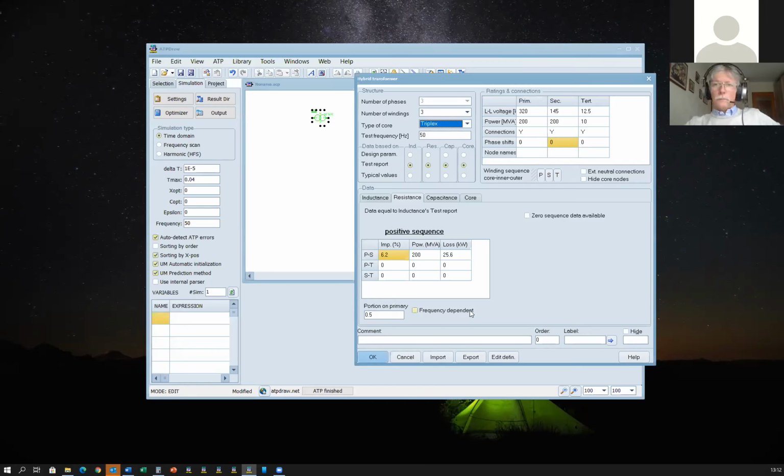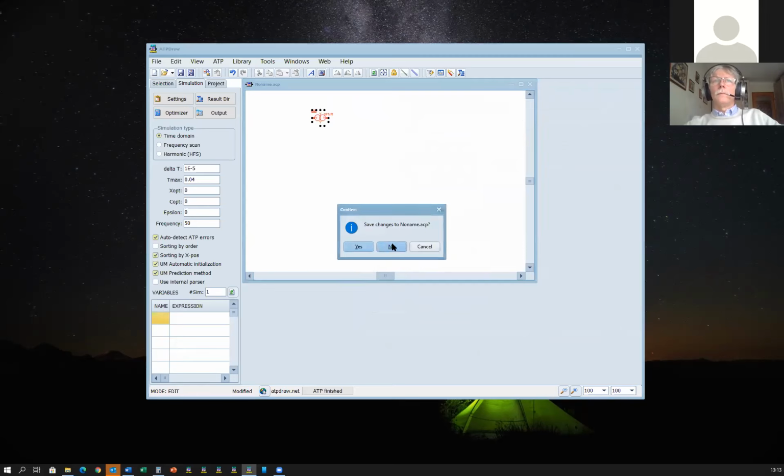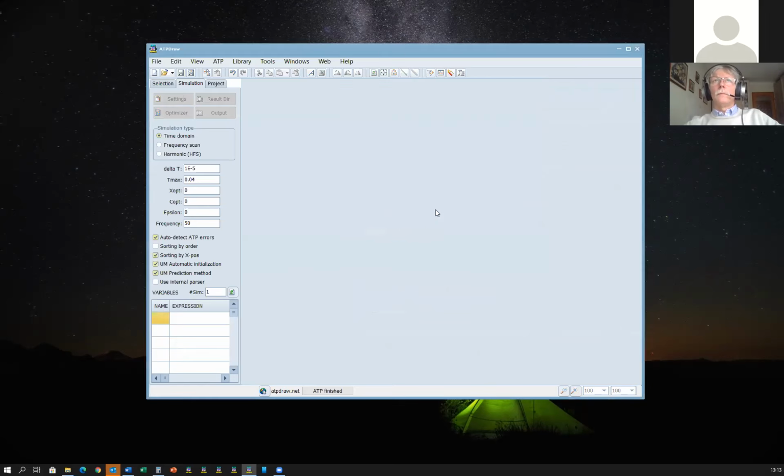Okay, we have a question also that has been already partially answered by Delcho. It says that test transformers age. How should the modeling change to account for the aging, or should it change at all? For dry type as well as oil filled, I have tested a lot of transformers. The power factor tests of the insulation are a major criteria to approve continued usage of transformer. Wondering what parameters change as transformers age and how that affects the response of the transformer to transients.